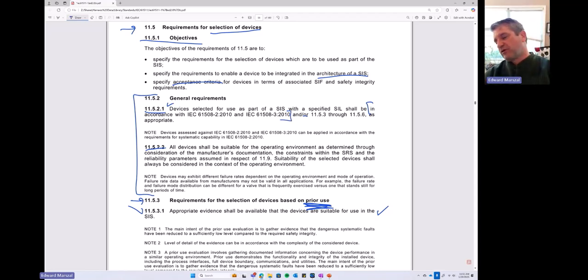It never says certified. And of course, as I mentioned earlier on in the discussion, we, and I do it myself, use certified as a shorthand because if you design and manufacture something in accordance with IEC 61508, almost always you're going to get a third party to certify it for you, because why else would your customers trust you?